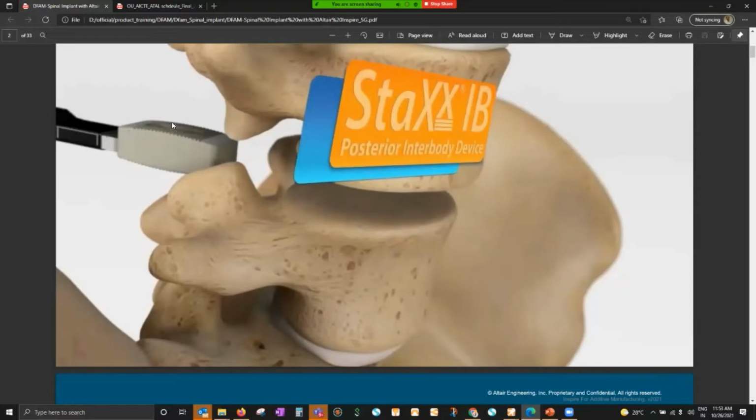And also this piece of spinal implant, or any implant for that matter, has to be as light as possible. The reason being, it will add additional weight to your body, and of course you don't want to carry extra load, and you don't want to load your spine with some extra piece of heavy metal, right? So it has to be extremely light, as light as possible. But at the same time, during insertion as well as during placement and after placement, you don't want it to collapse. That is another important thing, because if it collapses, that means it has failed, and again you have to remove it, and there is a lot of complication.